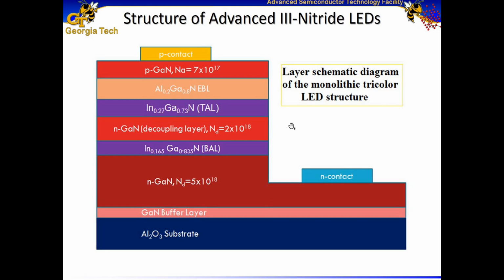If we increase the indium content to 20%, then it's going to give us a wavelength in the blue light range, around 450 nanometers, 460 nanometers, in that kind of range. If we further increase the indium content in the indium gallium nitride alloy to around 30%, then the corresponding band gap, and the wavelength it leads to, would be in the greenish light range.